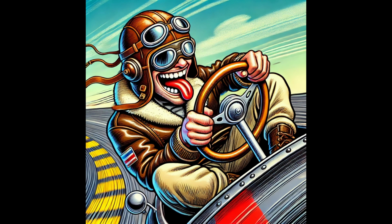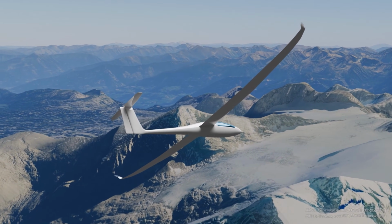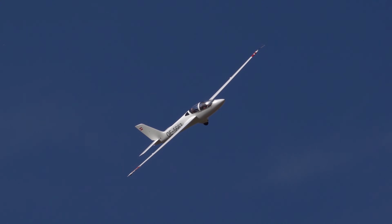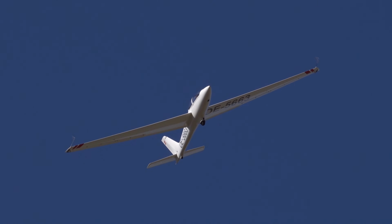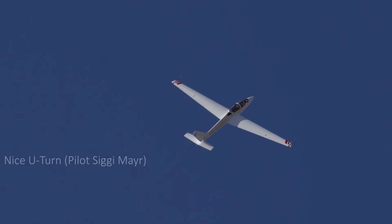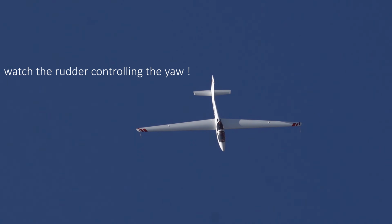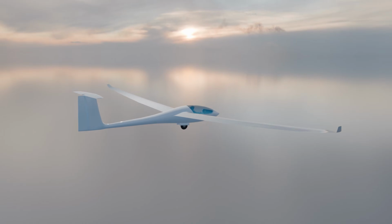What can we actually control in a glider? The direction? Sure, but not like in a car. It's all about juggling bank angle, yaw and pitch in the correct way. What about height? Well, we can't just decide to fly up. We can pitch up or down and see what happens. When we use the elevator, it always comes with a change in speed. But be careful, our glider can only fly within a certain speed range.